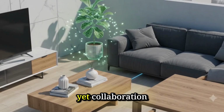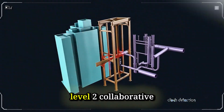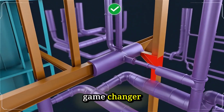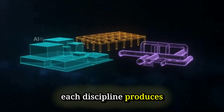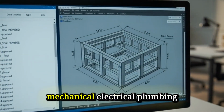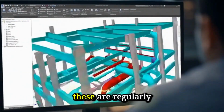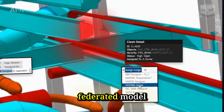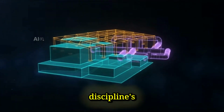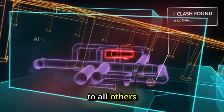Progress, but not yet collaboration. Level 2, collaborative BIM. This is the game changer. Each discipline produces its own three-dimensional BIM model: architecture, structure, mechanical, electrical, plumbing. These are regularly combined into a federated model. Clash detection runs automatically. Changes in one discipline's model are visible to all others.